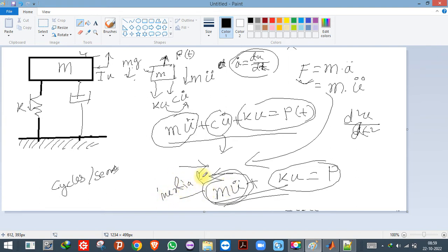That's why you may have observed that if the building is only a 1 story or 2 story building, we barely go for structural dynamics, what we call earthquake analysis, for such buildings, because the mass of the building is much less, isn't it?